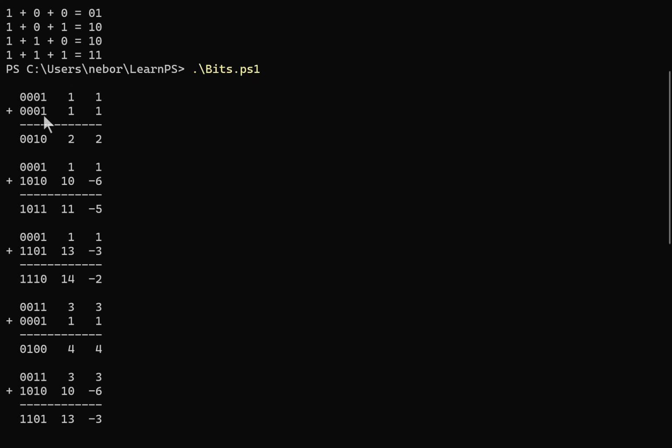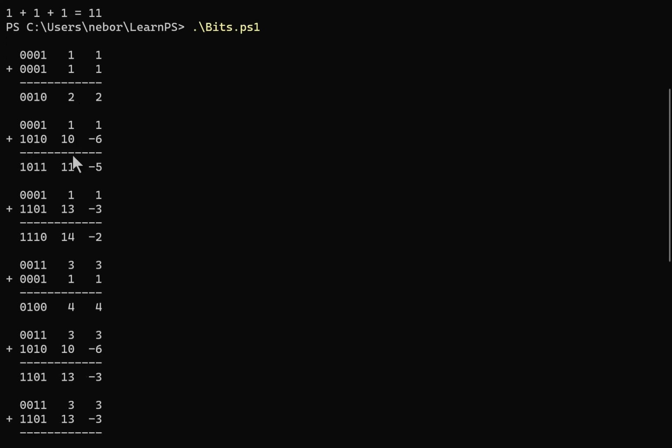So we have this pattern of bits, and we've just done our bitwise operations. And by just using our half adders and full adders all wired up a certain way, we indeed get 2. And when we convert that back to decimal, that's what we see. We add 1 and 10, and we get 11. Again, we just used the half adders and the full adders, which were built out of logic gates, and ended up with a certain pattern of bits. As far as the computer is concerned, all we're doing is basic logic operations on bits. There's no math here really per se, except that basic Boolean logic.